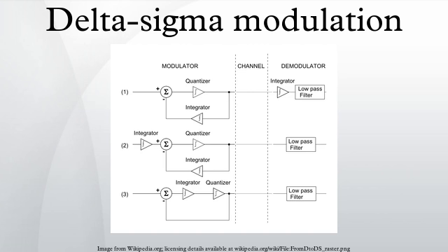In fact, the decimation filter put after the modulator not only filters the whole sampled signal in the band of interest, but also reduces the frequency of the signal, increasing its resolution. This is obtained by a sort of averaging of the higher data rate bitstream.